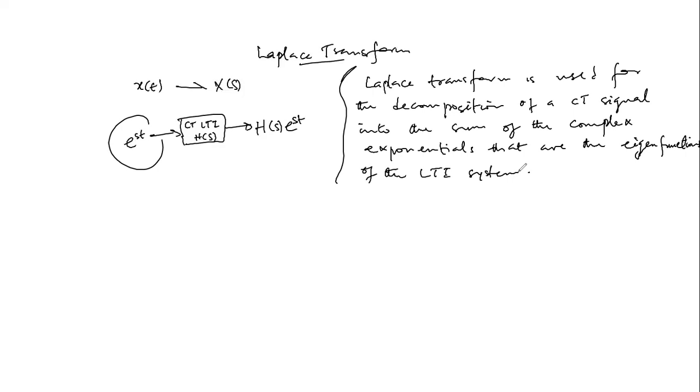So the implication is, since the Laplace transform is the sum of the complex exponentials that are the eigenfunctions of an LTI system, it therefore implies that the Laplace transform can be used to evaluate the output of any type of input due to the ease of the evaluation of the eigenfunction.